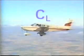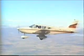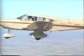The coefficient of lift is determined by the airfoil's shape and angle of attack. It's simply the ratio of the dynamic pressure generated by the wing to the surrounding static pressure. This value measures how efficiently a wing converts dynamic pressure into lift. The coefficient of lift value derived for each angle of attack is determined by wind tunnel tests, where all of the other variables in the lift equation are known.